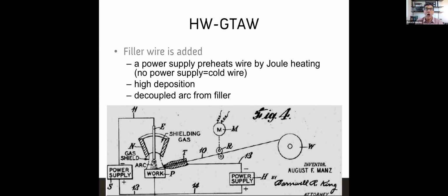But in the hot wire process, I'm putting the wire right at the melting temperature, zero superheat. And I can put a lot of wire. So I can make a weld that is relatively big, a big cross section. But the amount of heat I put into that weld is just the mathematical minimum to put the melting in, right? So the heat input in this case would be relatively low despite the large cross section. So here's the paradox. Hot wire can give you a cold weld.